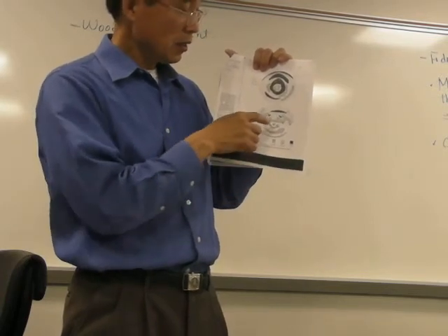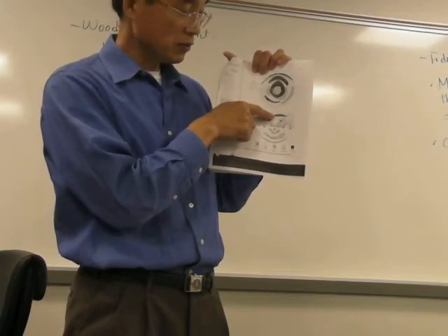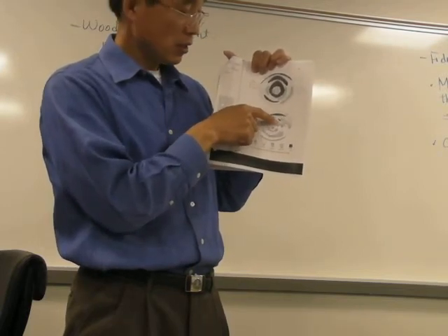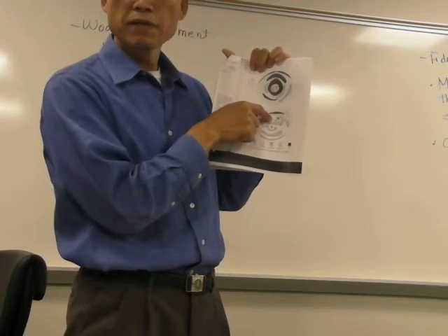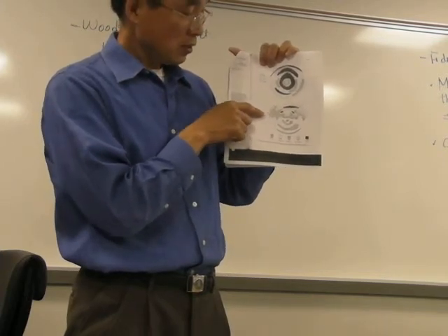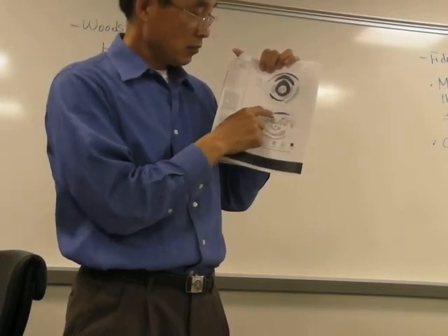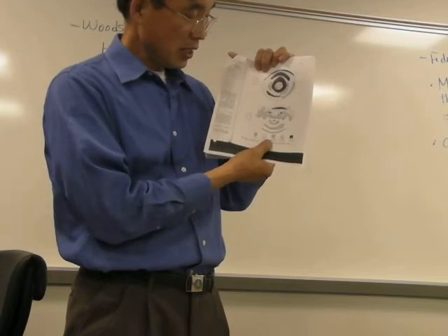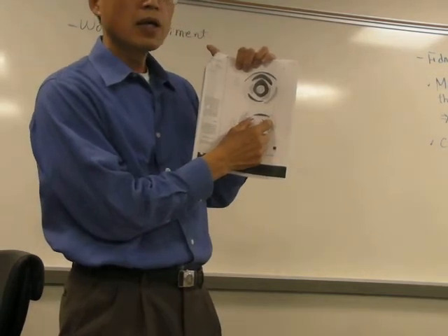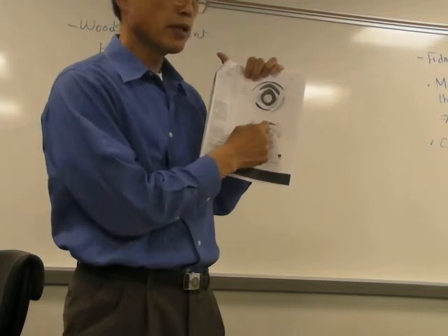Okay. Then you can see somewhere in here, the black area, ARF is less than 0.125, very effective vibration screening. And those dotted areas are where ARF is 0.25 to 0.125. But look at those areas on the left side and right side. Mostly they are hatched areas. That means ARF was somewhere 0.5 to 0.25. So those areas actually have much higher amplitude than in this area.